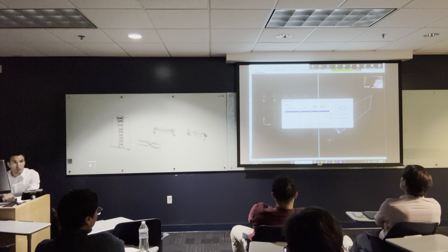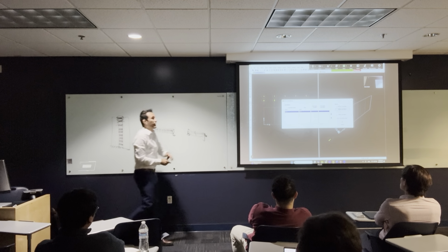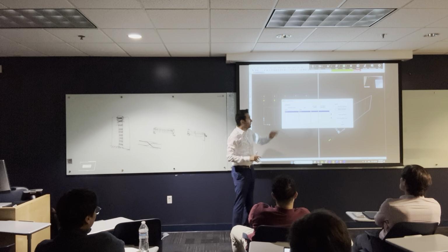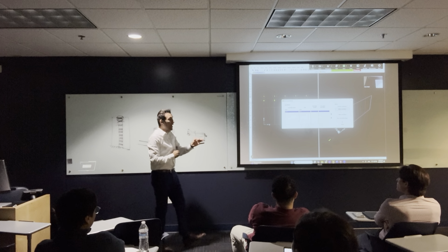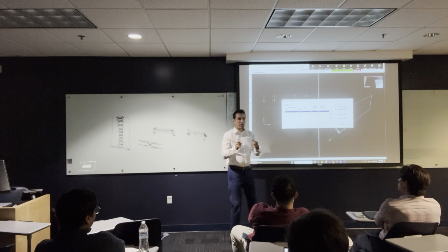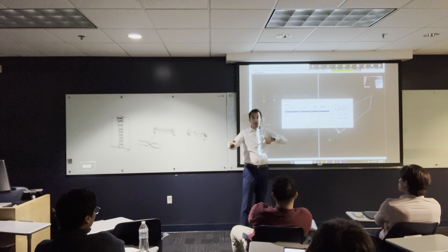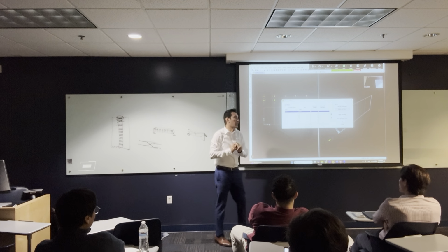So right now, there's no own weight that's going to be calculated in this load. However, let's keep it for now. I'm going to keep it as 1 and say modify, and see what's going to happen. Let's say you forget to put this. Let's see how this is going to affect our analysis, okay? So what is going to happen now? SAP 2000 is going to calculate the own weight and also the dead loads that you are going to put later in the same load case and run both of them together. Okay, that's what's going to happen.